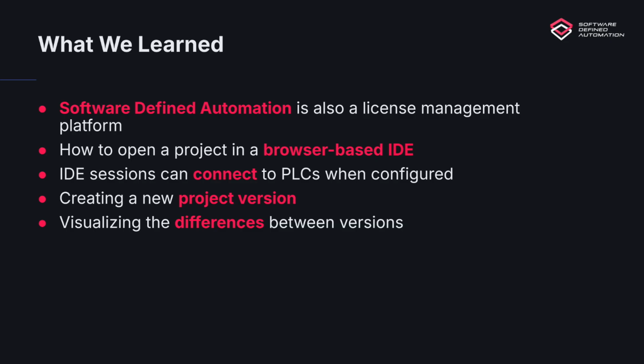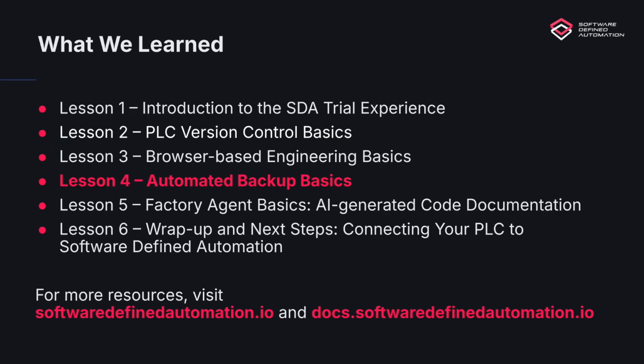In this lesson, we learned that software-defined automation is also a license management platform, which facilitates the process of working with multiple engineers on similar projects. I showed how to open a project in our browser-based engineering tool, which is IDE as a service. We saw that IDE sessions can also connect to PLCs when they are configured with the connectivity gateways. We then edited the project and created a new version of it. Finally, we validated our changes in the SDA console using a project diffing. In the next lesson, you're going to learn how to configure automated backup for your PLC projects.